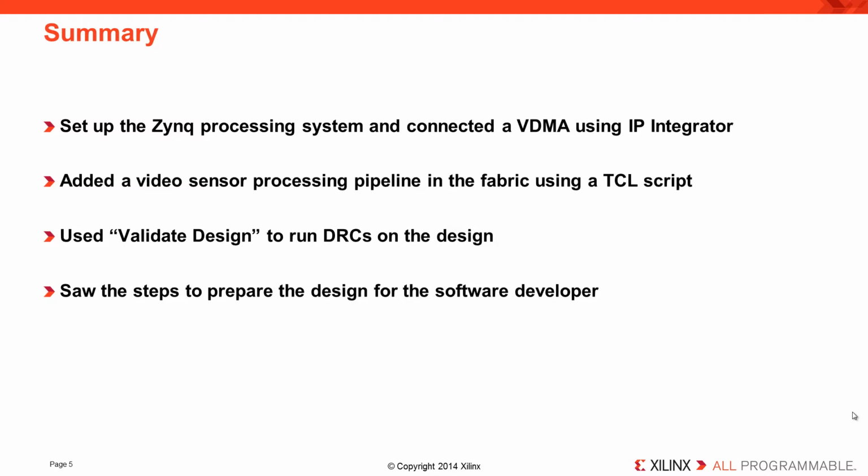So in this video, we saw how we set up the Zynq processing system and connected a VDMA using IP Integrator. Then we added a video sensor processing pipeline in the fabric using a Tcl script. We used validate design to run design rule checks on the design. And then we saw the steps to prepare the design for the software developer.